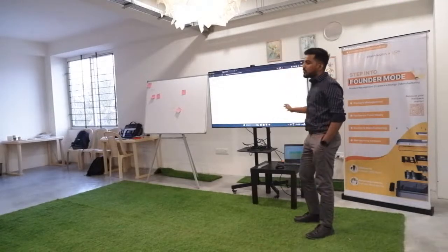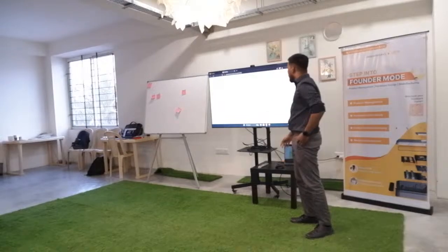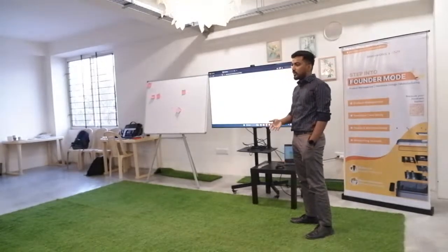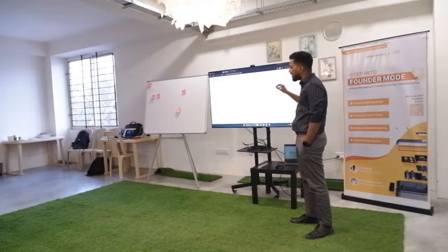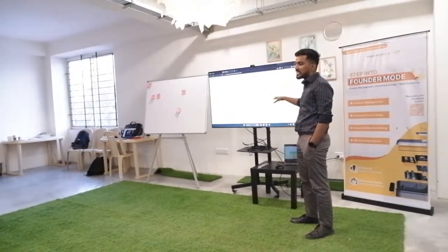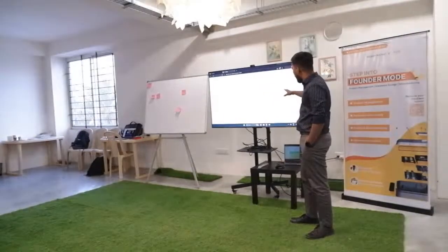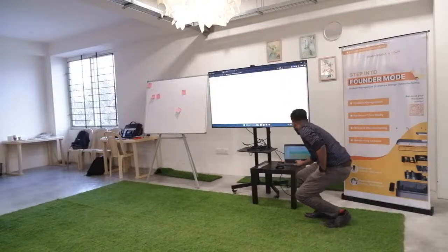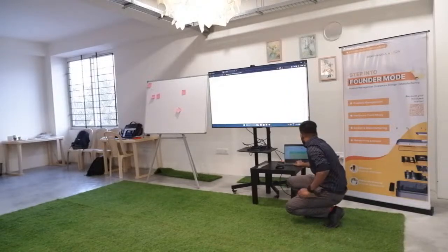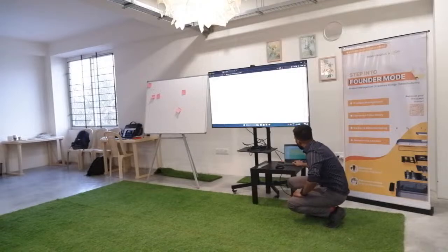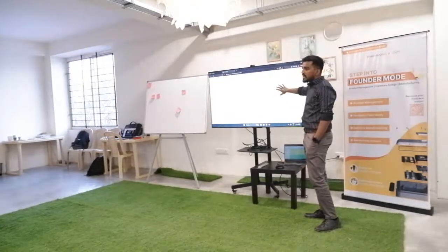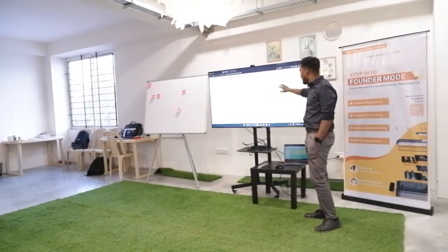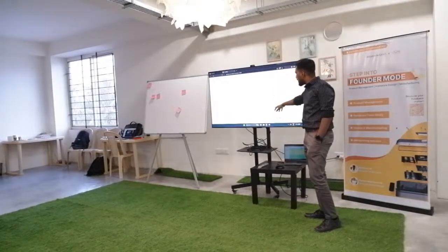Then the other feature I use the most is the assembly. So here, like I told you, you don't want to get involved in the process. You make sure you put the exact part number, exact reference number, and exact value here. And you can see all the components used in a particular single project. So these are the number of components that are used, and you can see the color marking. Those are DNP, so I don't want them to be soldered. And you can see how many components they have received.